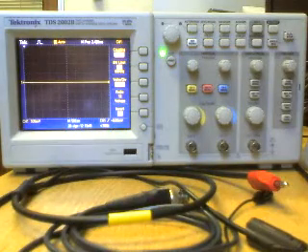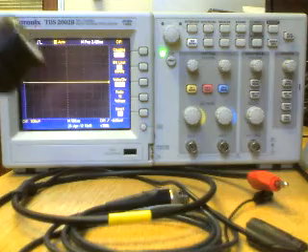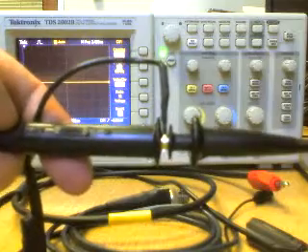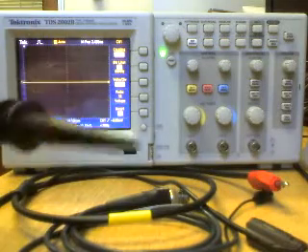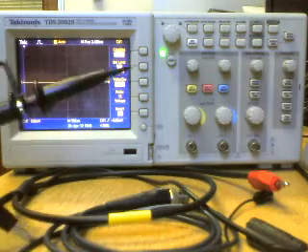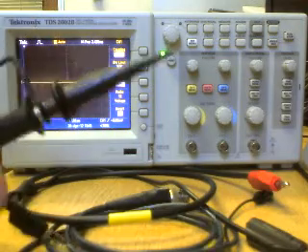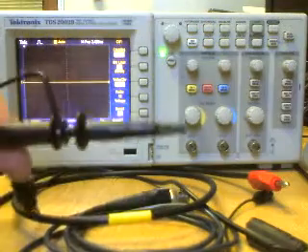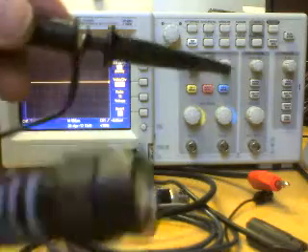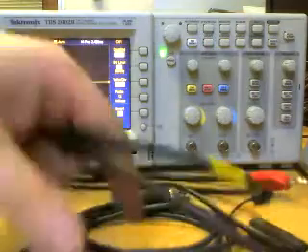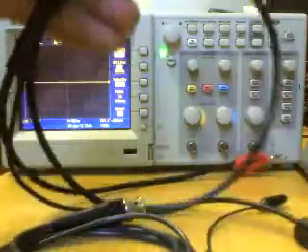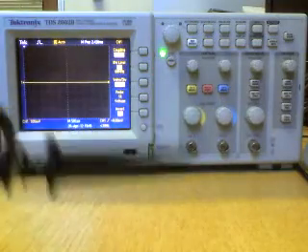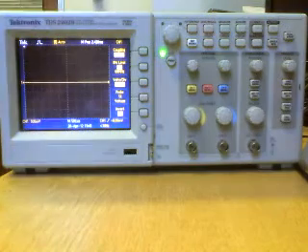Well, if you have, again, 1 volt at that end and the little switch on the side, if you switch that to X1, if you have 1 volt here, you get 1 volt at the end. If you switch it to X10, this little switch here, if you have 1 volt here, you get 0.1 volts here. So this probe is a bit like having 2 of these. You have an X1 and an X10 all in one handy tool, which is why most of the toolkits contain these, because you can use them both.